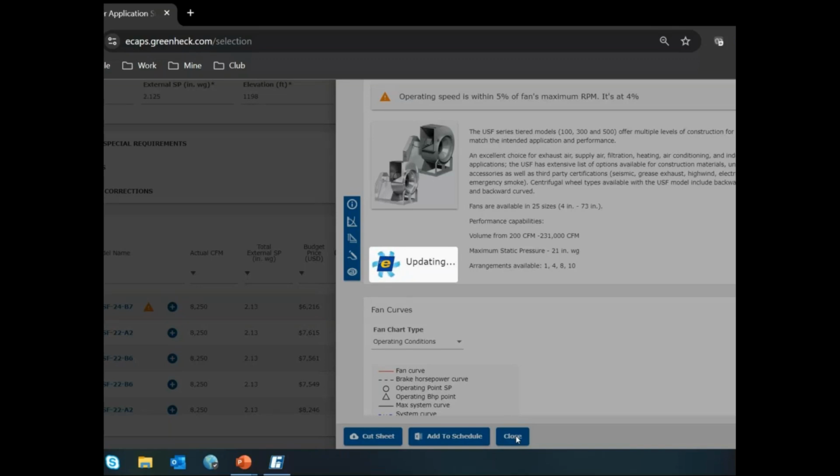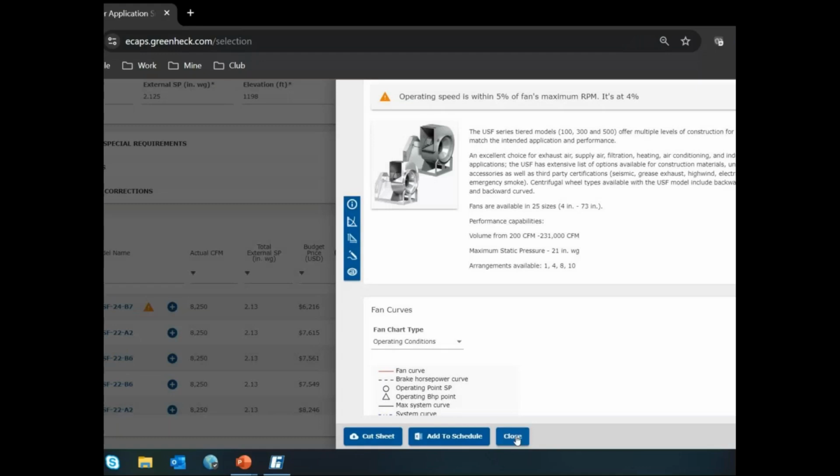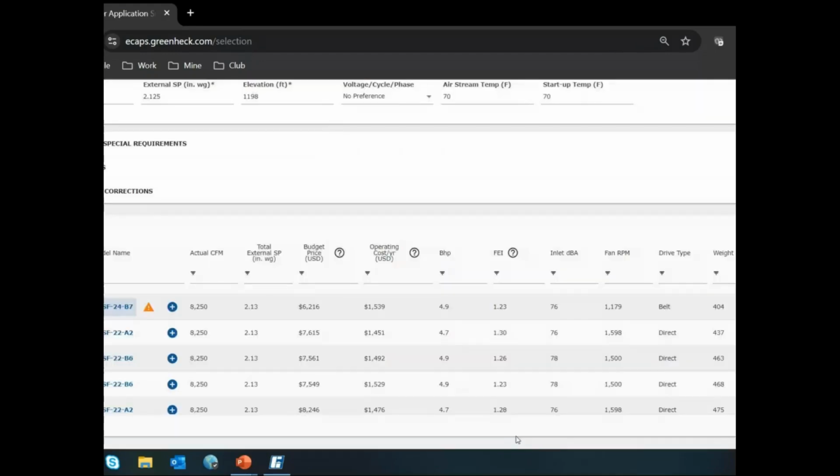And then one more question was, what temperatures are you referring to when you say high temperature airstream? Okay, that's a good one. Go ahead. I think most of the Greenheck fans will be good up to 140, and then I think anything over 250 Fahrenheit is what we consider high temp. I believe. Is that right, or is it less than that? It depends on the type of fan. Like power roof ventilators, that's that spun aluminum stuff.